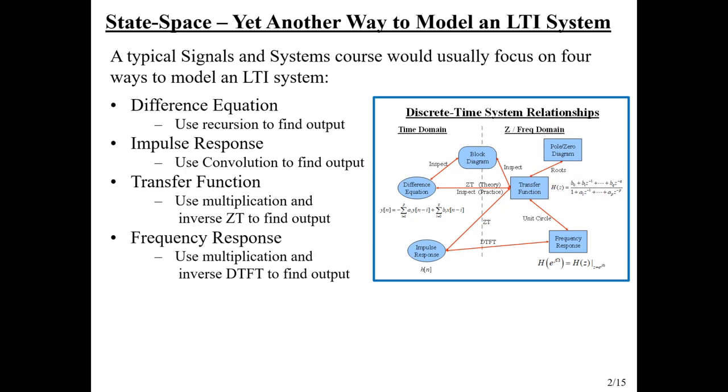And then we have the frequency response, which is down here also on the frequency domain side. We get it from the transfer function. We replace z by e to the j omega, and here I'm back to using capital omega as our discrete time frequency. The previous two notes were based on a book that used theta, so I used that there.